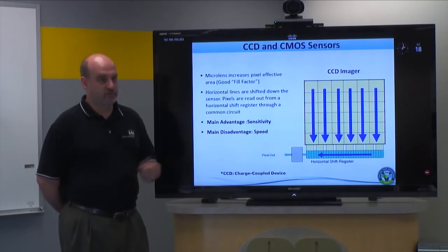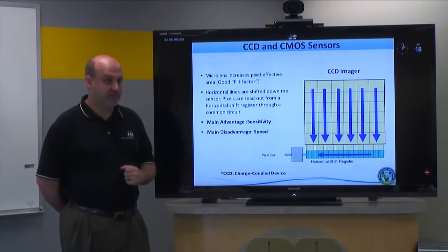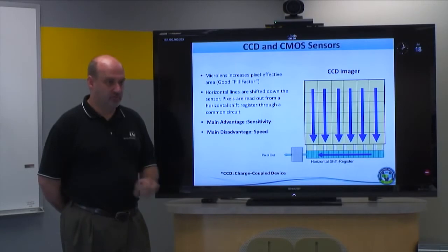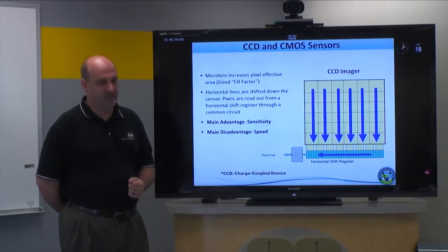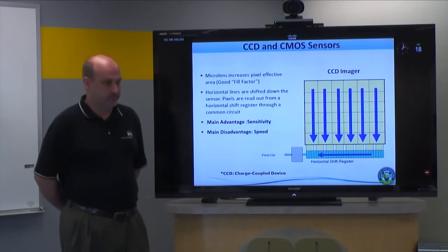Now, they, of course, try to keep the resistance low and keep that power down, but by nature, you are moving current on the face of the CCD, and that is thus developing power on the CCD face itself. For something like the Kodak 4 megapixel sensor, there's roughly half an amp flowing to read out 4 million pixels 15 times a second, and that half an amp then makes a little over a watt on the face of the surface of the sensor.